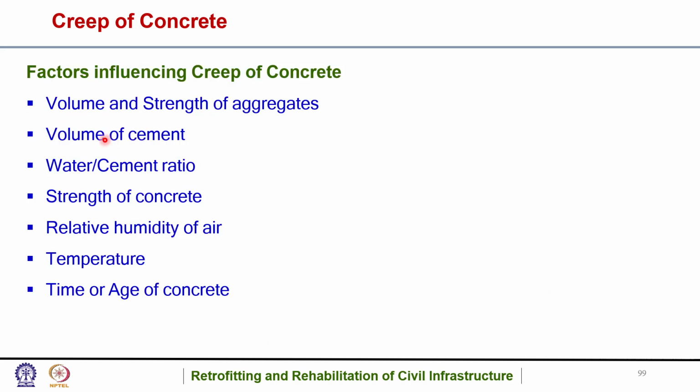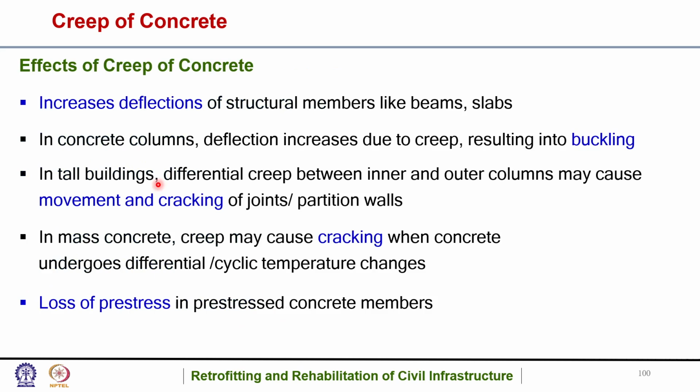So the various factors influencing creep of concrete are volume and strength of aggregates, volume of cement, water cement ratio, relative humidity of air, temperature, and time or age of concrete. So these are some of the factors influencing creep.